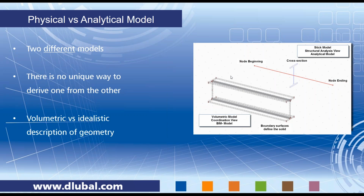What we see below here is what we would also get in the so-called IFC coordination view. So we get a volumetric model, and this above would be the IFC structural analysis view. These are two different models, and IFC does not necessarily take care of the transition from one model to the other one. So this has to be done either in the BIM software or afterwards in the structural analysis software.